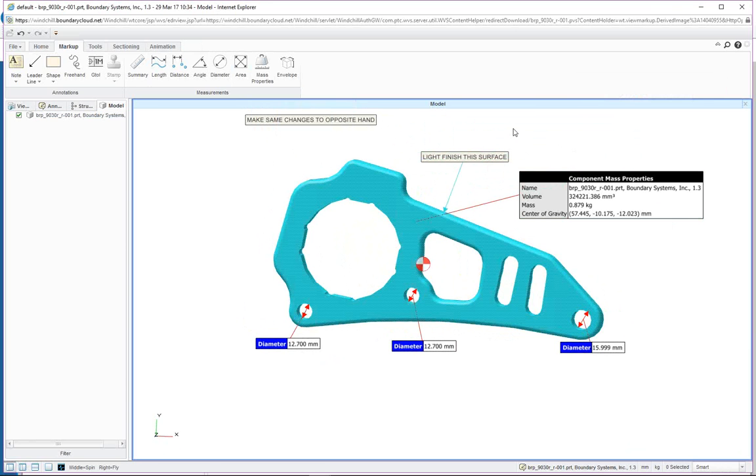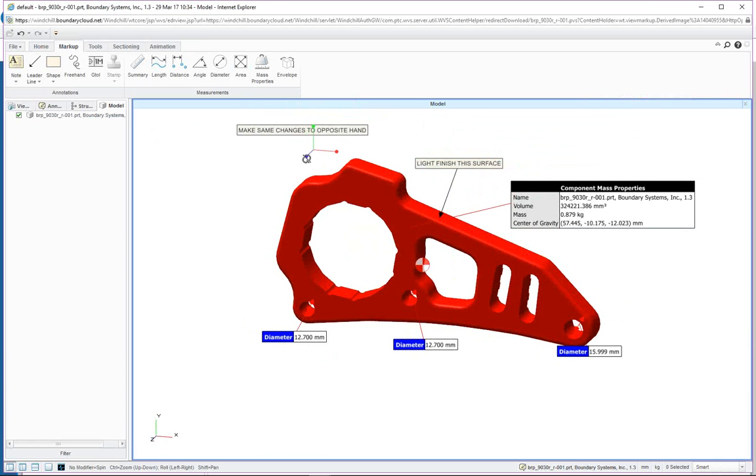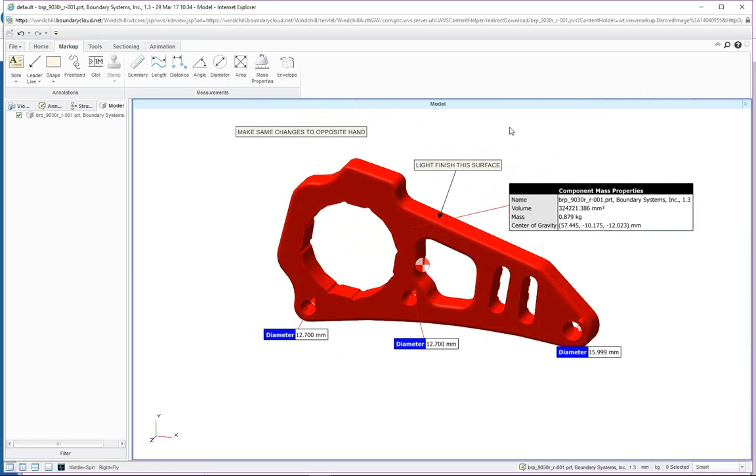So now my suggestion when you start doing a lot of this is, just like if you were doing an exploded view inside of Creo and you want to actually show it on the drawing, find a view that you want and lock it in, and then create your orientations from that. That way you're looking at things pretty cleanly when you're actually viewing the information.